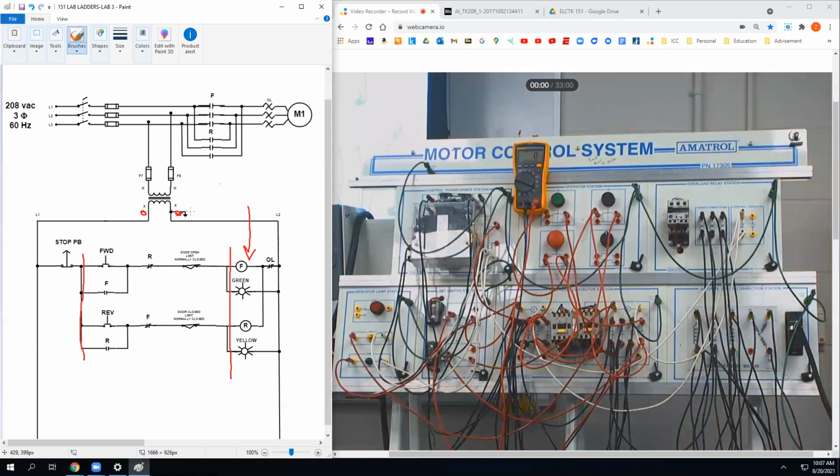That's the difference between us and people that shotgun it. We have a plan, right? They're just like, oh, maybe I'll run over there and check that, and they waste all day. So let's say we had a big thing like that with a whole circuit all over it. If nothing's working at all, would you just go to the place you're nearest to, see if there's even current there, for continuity, and then think about how the circuit would be laid out and work from there? Yeah. There's a lot of variables to it though.